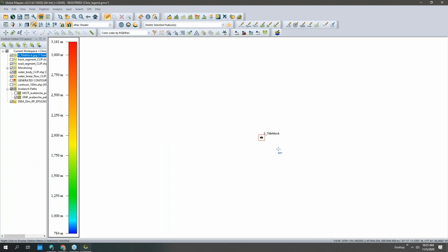So I've actually chosen to add this as a picture point. There was a dialog option that gives me options. I can rectify this data to bring it in. In this case, by adding it as a picture point, I can actually place it in the geospatial location that I want and kind of fake the coordinates. So this is probably the easiest way to do this.